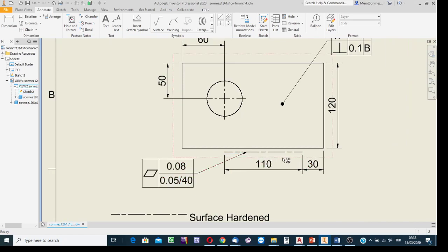What is the meaning? It is to say something relative to the right side surface of the body. By the way, on the top view, this line corresponds to the projection of the right side surface. That line corresponds to the projection of the front side surface of the object.